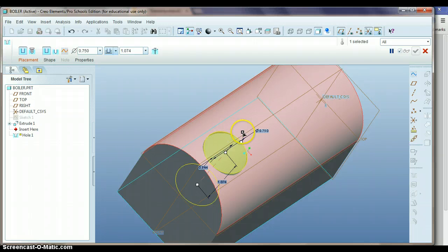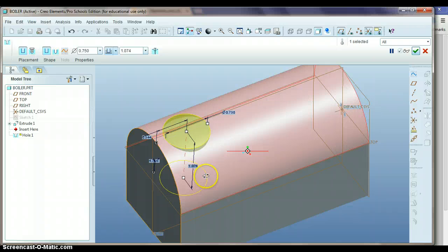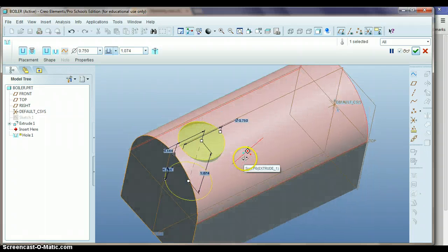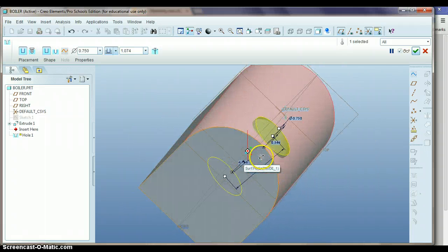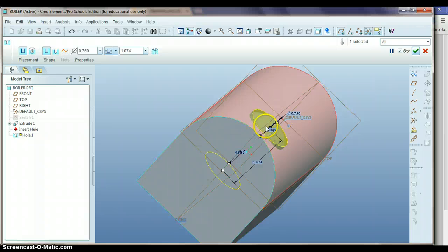And this one I'm going to drag to this center datum plane right here and let go. Now a couple things will happen here. You'll see it might be on this end, but there should be a number with degrees, and that tells us the angle that this is at. If you look at it, it's not exactly straight on the very top. So I'm going to click on this angle here and change it to 0 and press enter.